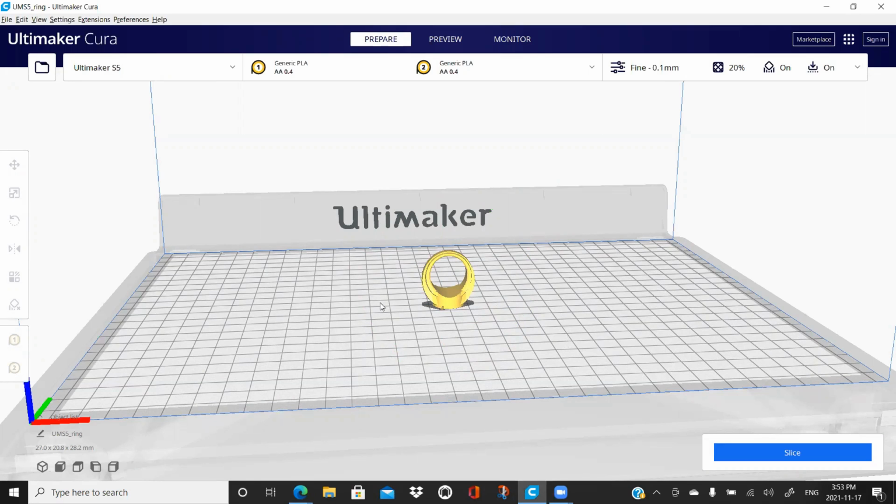In truth, this actual overhang is not that much of an angle, and so you could print it without support. In fact, I'll show you all the actual copy of this printed in just a moment, and I actually printed it without support. But this way, you're not going to need as much because you really just need it for the top thinnest part, so you're minimizing the risk of overhang there. So the next step is going to be to add our supports.